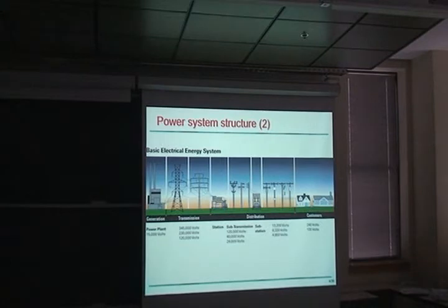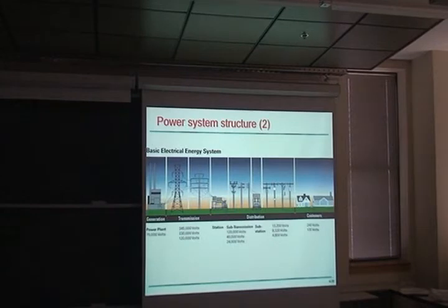So there's an economic trade-off. What they do to produce DC is AC is rectified to become DC, transmitted over long distance, and then converted back to AC using power electronics at both ends. Okay, it's not done mechanically. It's not done mechanically, it's done with power electronics.